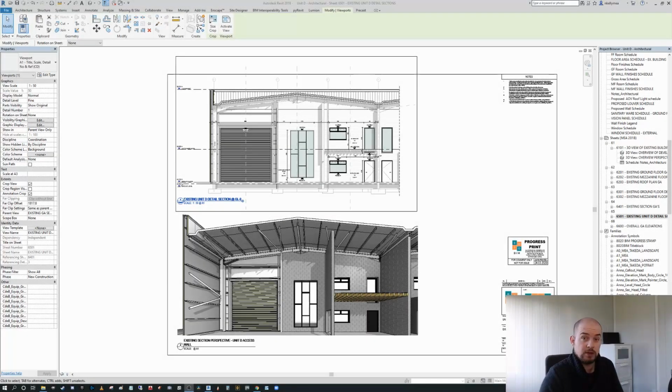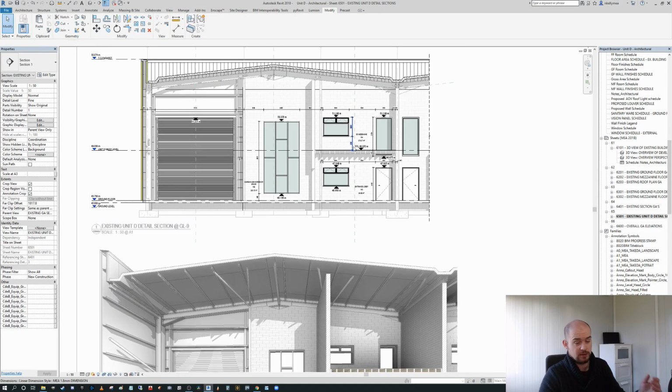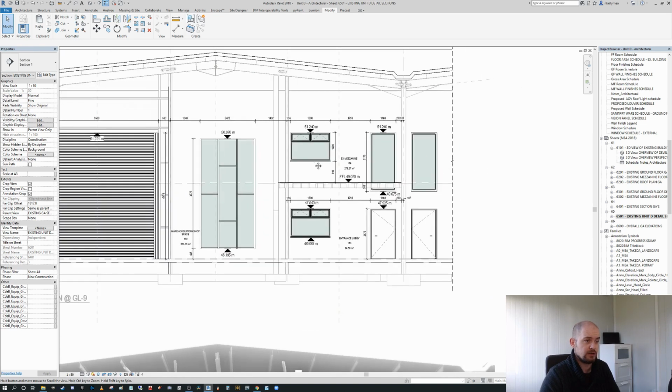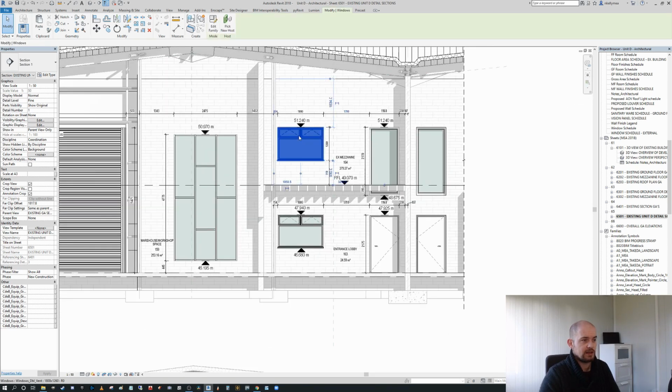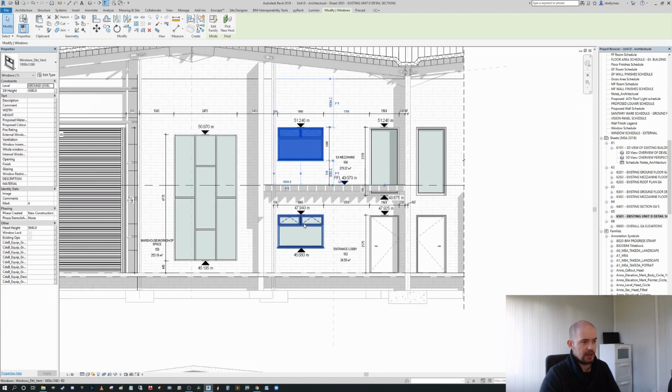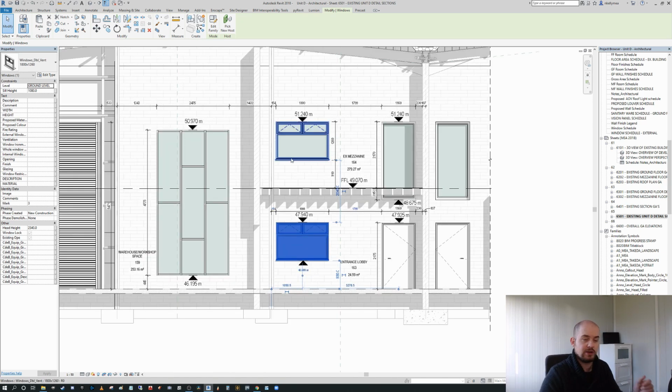Step 10, how to use the common selection methods in Revit. So this is something that is probably very familiar for the majority of people watching, but when you select something in Revit, okay, you cannot maintain a multiple selection by just clicking. So historically, if you're a CAD user, you would have been able to click multiple elements and it would continuously add to your collective selection, if that makes sense. But in Revit, it'll only select the individual items.